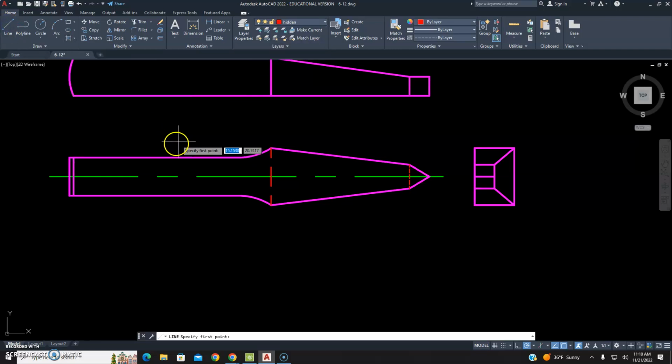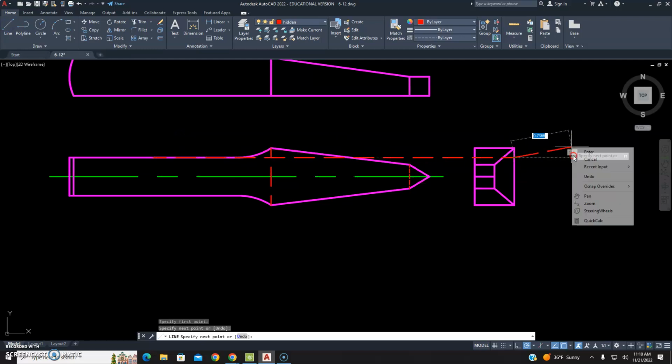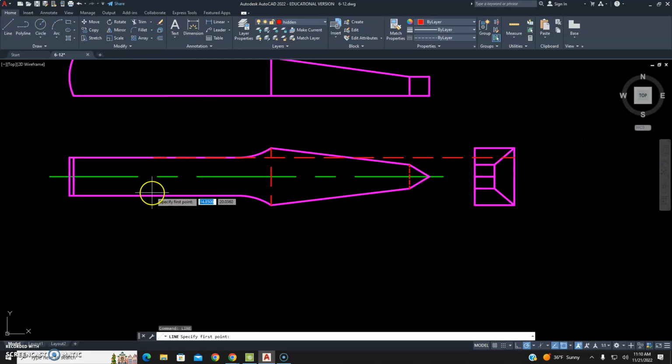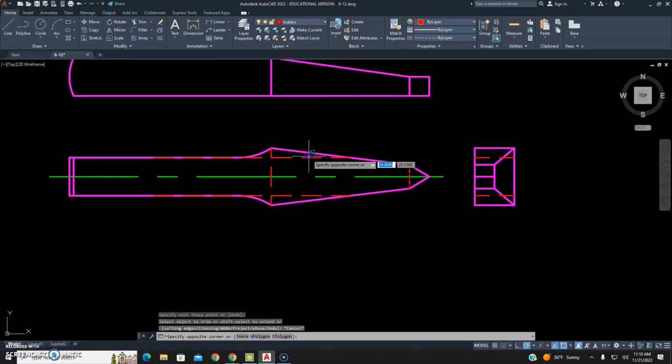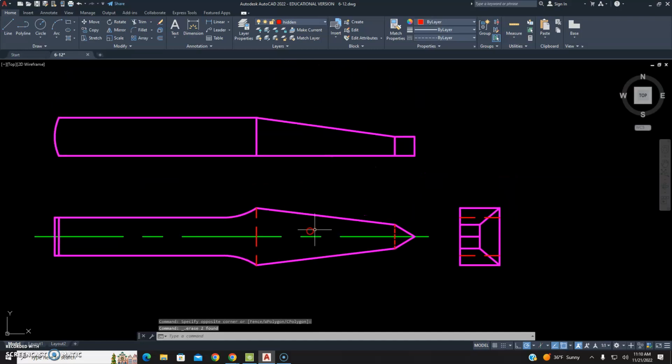So that's all of our visible lines, and then we need hidden lines to show the handle or the shaft or the shank end, depending upon what you want to call it. Few ways to do that. I find just bringing the hidden line straight up and over to be the best way to do it. Then we can just come in with our trim tool, remove what we don't need, and then just delete these two out of our drawing. And there we have our chisel.